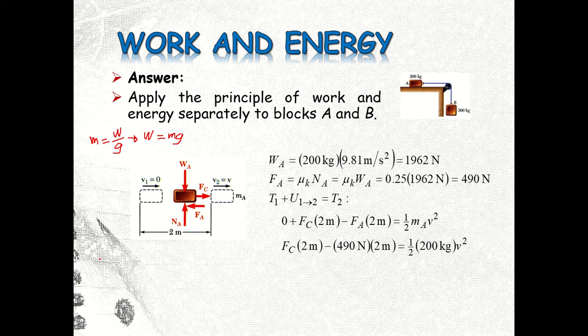Okay, and then we have the relationship between the normal force and the friction along the surface. They are related by this equation, class: the frictional force of the movement of block A, that is Fa, is equal to the product of the coefficient of friction, which is mu sub k, multiplied by the normal force. Okay, normal force, we call it Na.